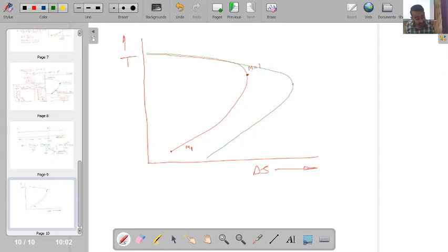But once again, this point remains at Mach number equal to 1 only, because the highest entropy point, from the nature of the equation or the nature of the curve, always has to correspond to Mach number equal to 1. So now you can interestingly see that in this portion, with Lmax length, you are able to reach the sonic condition.